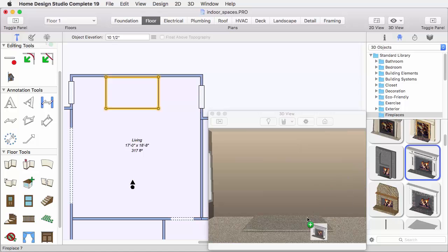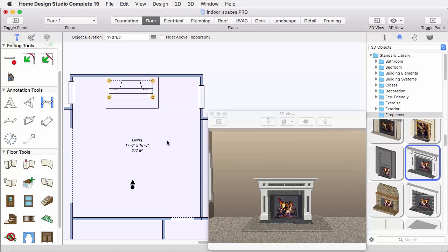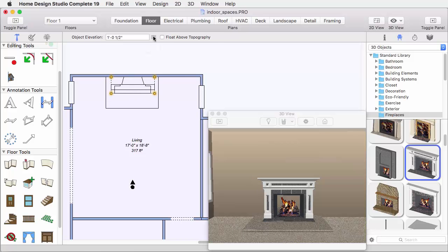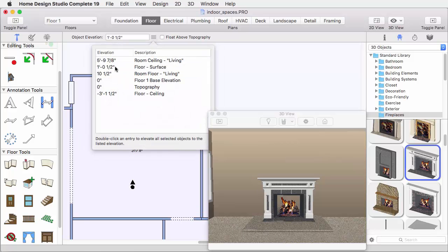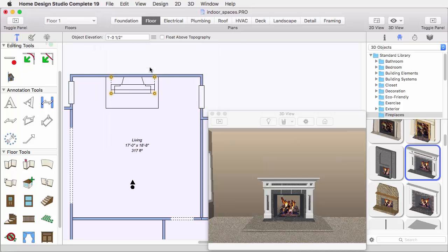If we go to Elevation Bar, you can see that it's automatically been placed on top of that floor section. You can also modify the floor sections by simply selecting a point or a segment, dragging it with your mouse and cursor, or using the arrow keys, you can nudge those segments or points in the drawing.